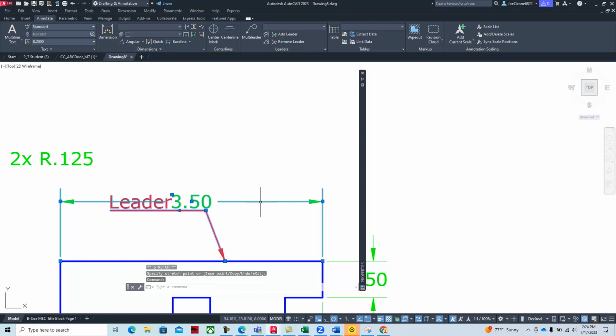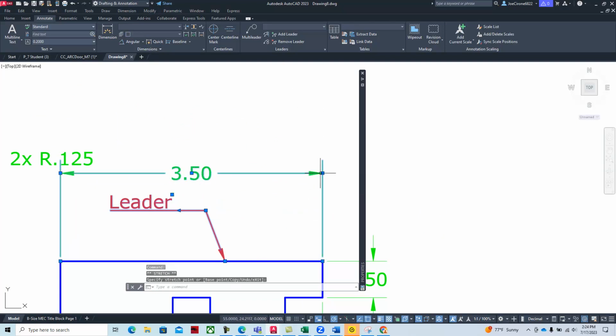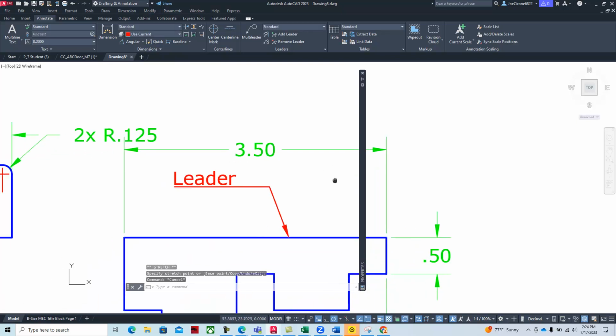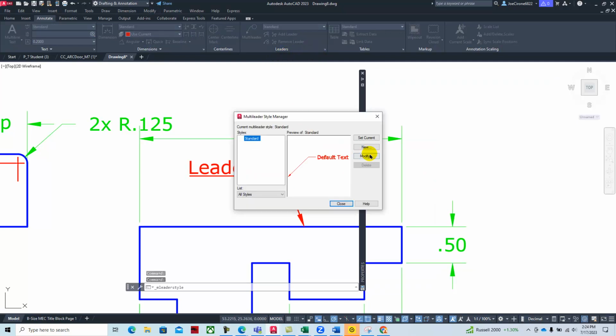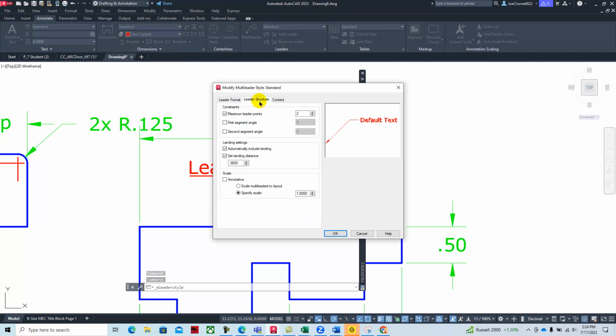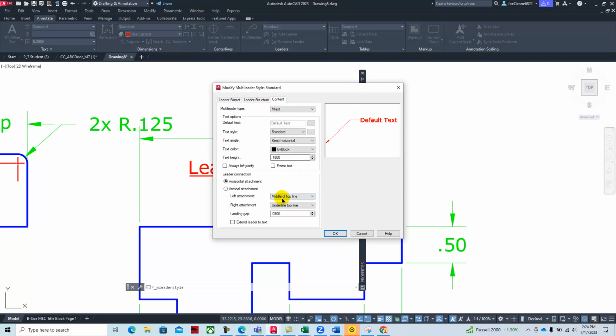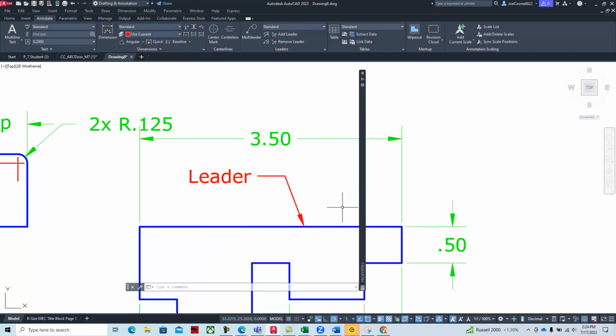And so the idea is to make, again, a neat drawing which indicates some of the things that are on there. It does have a leader style, and so when we look at the multi-leader and the style, you can see when you go left it's above versus when you go right. And so in the multi-leader style, what I typically do is to modify it so that the landing is the same, middle top of line and middle top of line, whether I go right or left. And then I can apply that. And so that's what's customizable about our dimensions.